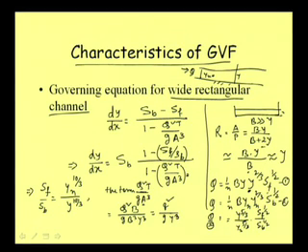Now if we recall our earlier classes, we defined the critical depth for a rectangular channel. Let me write here, we defined that YC, the critical depth, is nothing but q square by g, whole to the power 1/3.